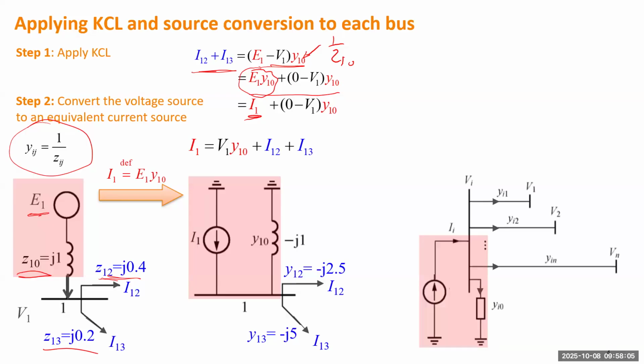Okay, next we can generalize this design with this figure. For any bus, no matter how many branches, we can always take this unified design. For this unified design, we have one equation to hold. The left side is the total current going into the bus. The first item on the right is the current going to the ground through the admittance representing the original internal impedance.